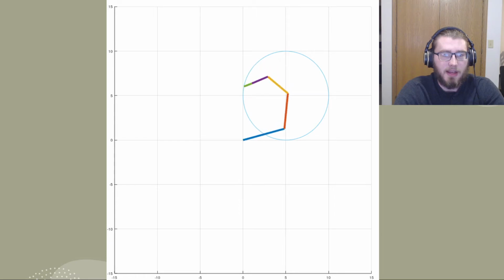And you can see over time, it does keep tracing it. And what's happening is at each update step, we're calculating the next position along the parametric function, which is in this case a circle. And we're having the solver actually solve inverse kinematics such that the robotic arm puts its end effector at that location. So now we'll take a look at another function.